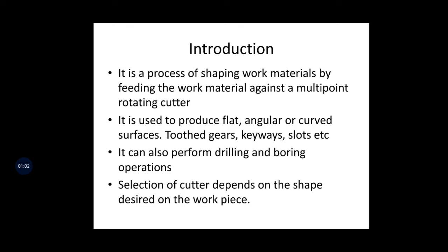So here the tool is also multi-point. It is not single point. The tool is a multi-point rotating cutter. It consists of so many cutting edges. This is called a milling cutter. But in the lathe we had a single point cutting tool, only one cutting edge. Milling can also perform drilling and boring operations. It depends upon the cutter and the desired workpiece, that is, the shape of the workpiece. That is the main important thing.